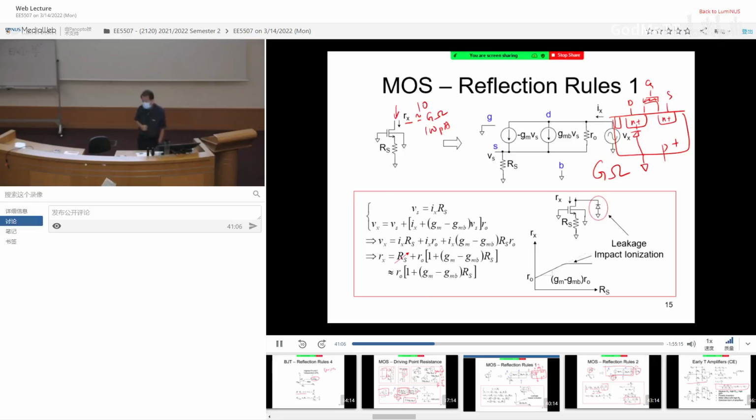Am I right? But how much did the reverse bias diode draw? Nanoampere. Right? So there is a reverse bias diode here that is already drawing nanoampere. So are you able to reach picoampere? Never. You can never reach picoampere. Because although this branch can give you picoampere, the diode branch gives you nanoampere. In total, you still end up with nanoampere.